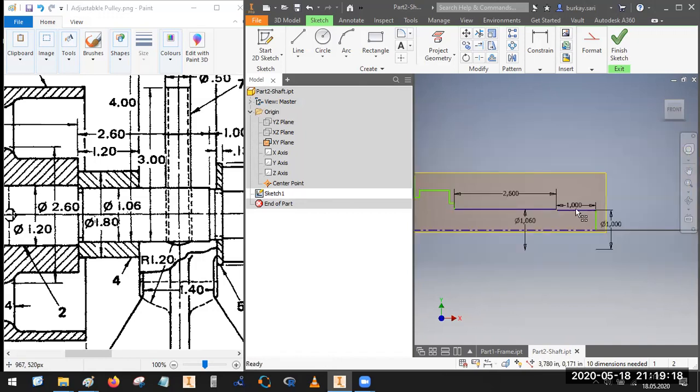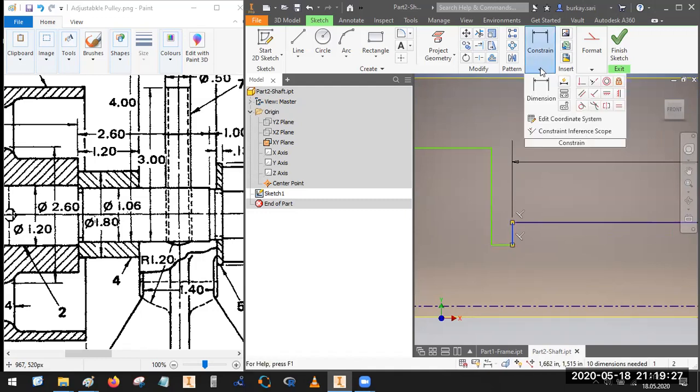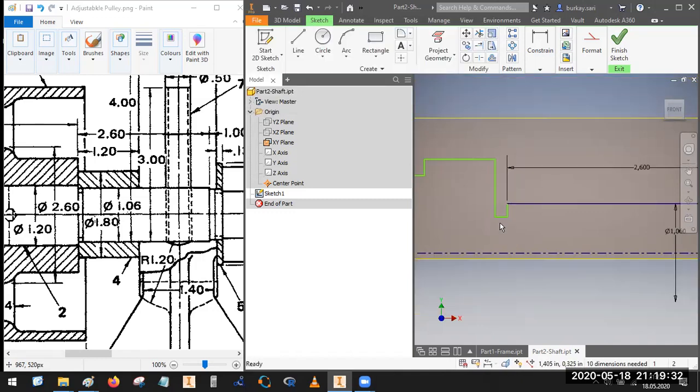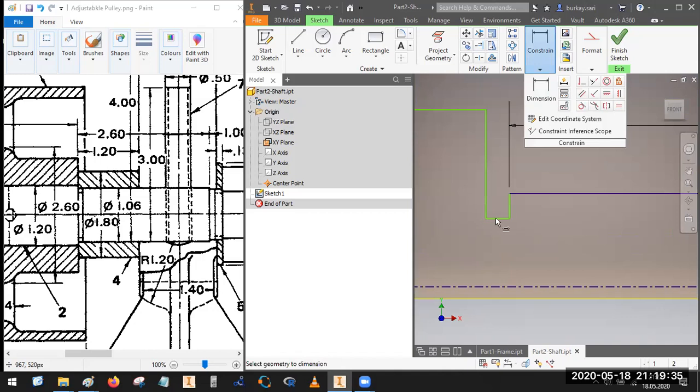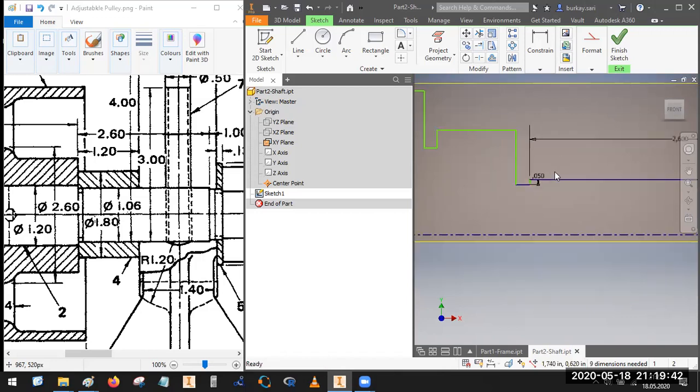I have an undercut at this point, which is down beside it. Here, we have a vertical constraint. If I have made a mistake about this one, I will just leave this distance about 0.05 inches. Just in case, I will delete it afterwards when I find the dimensions on the table of our part here.